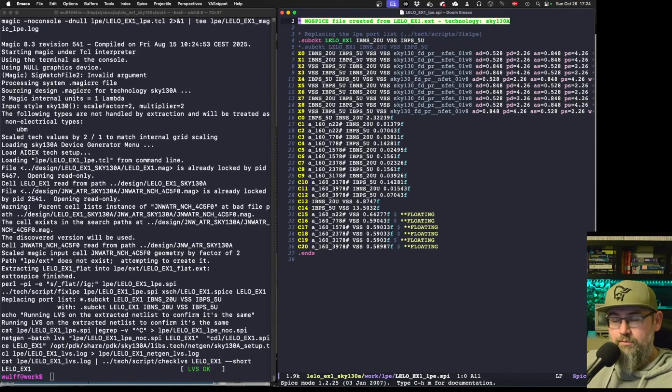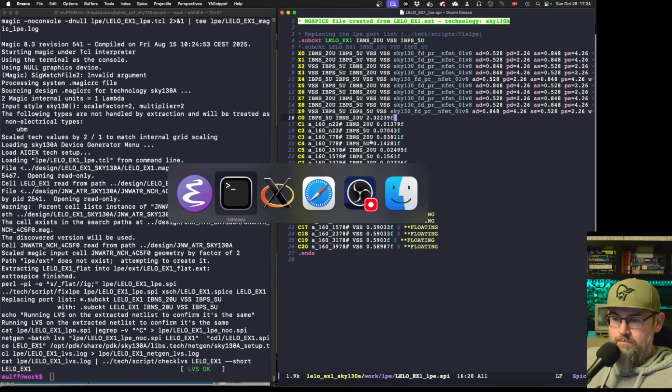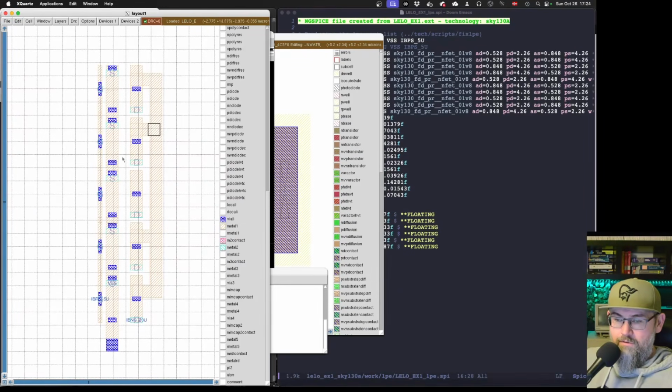There's not much difference between just a standard simulation and the simulation with capacitance, so that's okay. And here you can see that there is now a capacitance between the input net and the output net of about 2 femtofarads. And that's probably because they run parallel. Actually, let's try and change it. So let me make it a lot worse. Let's see, how do I make it smaller?